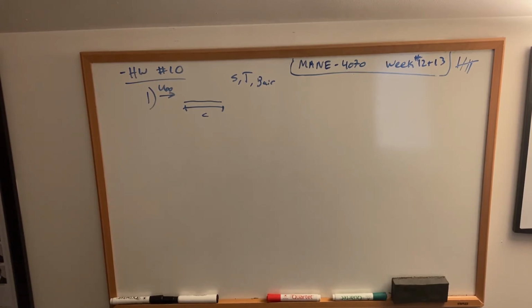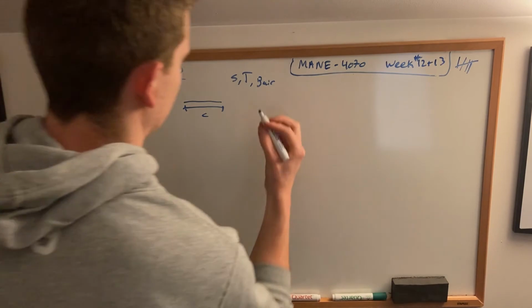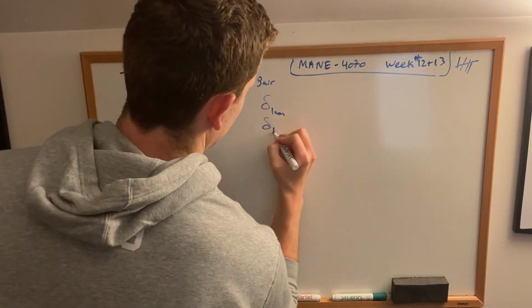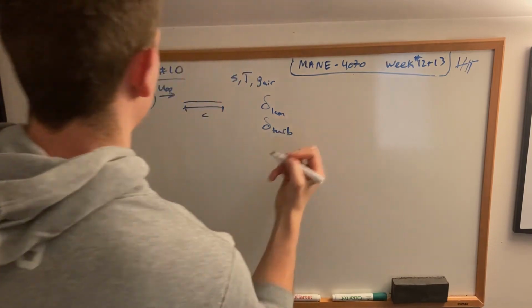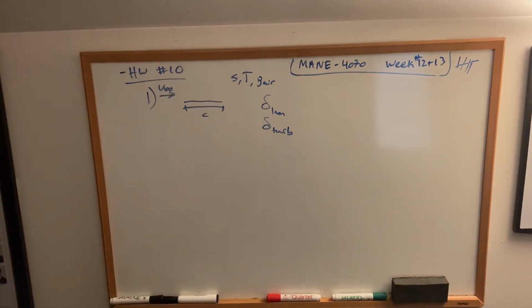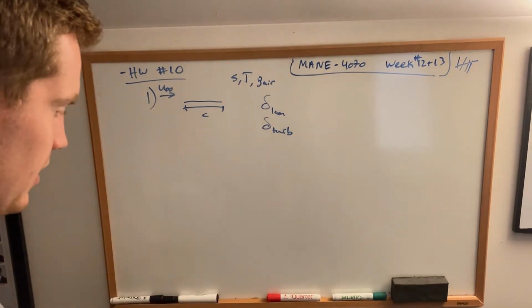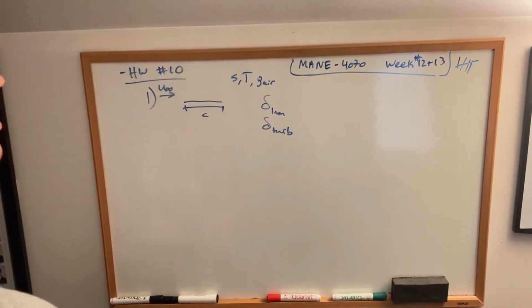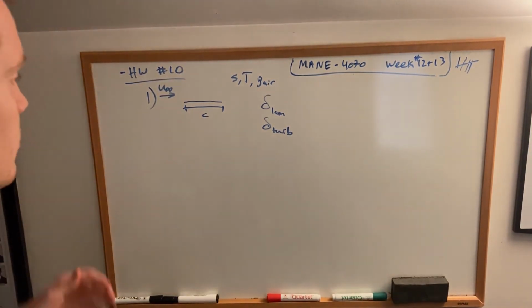But what's important to realize is that you have a couple of equations. You have equations for the boundary layer when it's turbulent and when it's laminar. So you then have to decide what regime you're in. There also is a possibility of a transitional regime, which I said to ignore. In that case, it's going to be approximated as some step function.